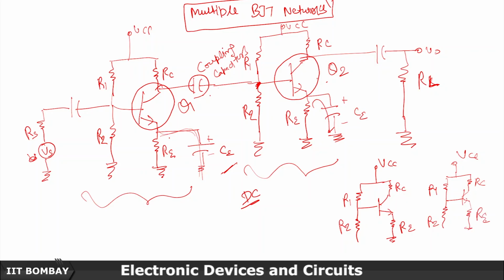So same as we did there. So this is input, this is something like that. Okay, so their independent resistance, their parameter of the transistor, whatever beta 1 and beta 2 is here, they will decide all these parameters, applied voltage, etc., their operating points.